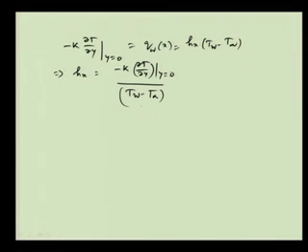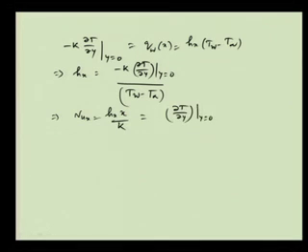So, the Nusselt number, from there, we can say that Nux is equal to hx x by k, and that we will write as minus, the k cancels. So, what we will get is ∂T/∂y at y equal to 0 divided by (Tw minus T∞) by x.